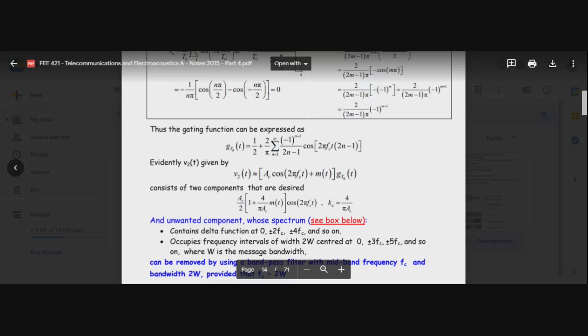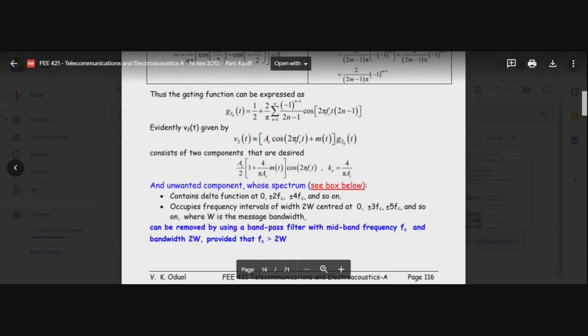But the details that you're having here, even after this, you probably won't remember. You need to get a piece of paper and start calculating them. Again, not to be memorized, because these things you memorize, but maybe 3 or so months from now, you'll have forgotten. But what you should remember is that one way of generating an AM signal is by taking the message, adding it to a carrier, passing the thing through a diode, and following that with a filter.